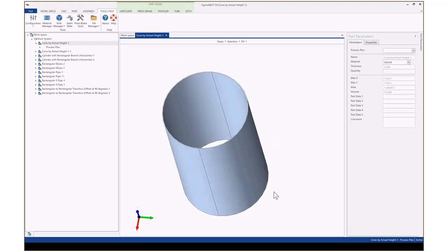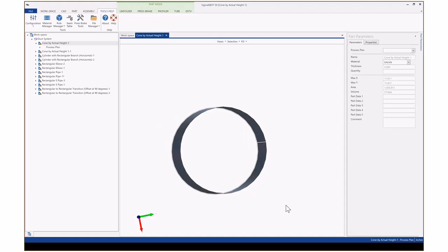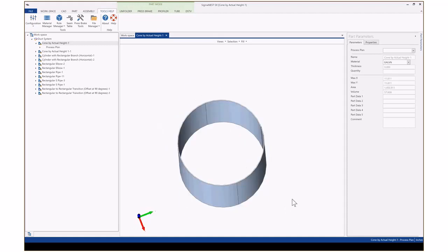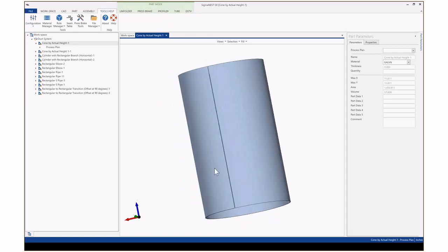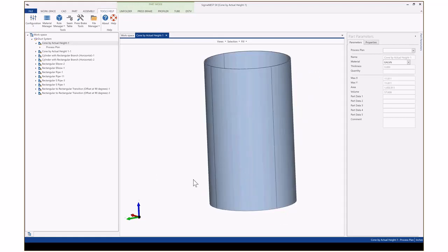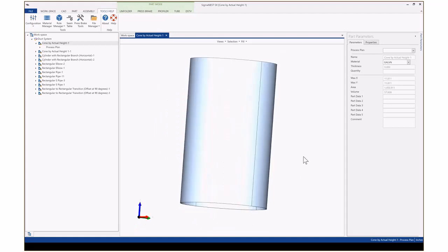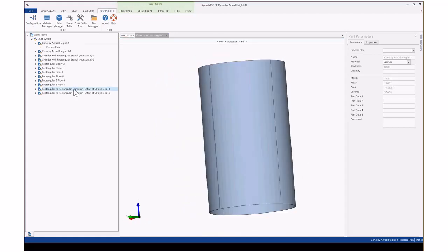Yeah, you'd add whatever materials you want. I showed Anthony when I was installing it on his machine, but there is a way to import existing materials from Sigmatek, and you don't have to recreate everything from scratch. There's a little bit of an importer or a utility to help with that, but you do supply the K factors based off of what you want to use, and then once you really set that up initially, you're good from then on.